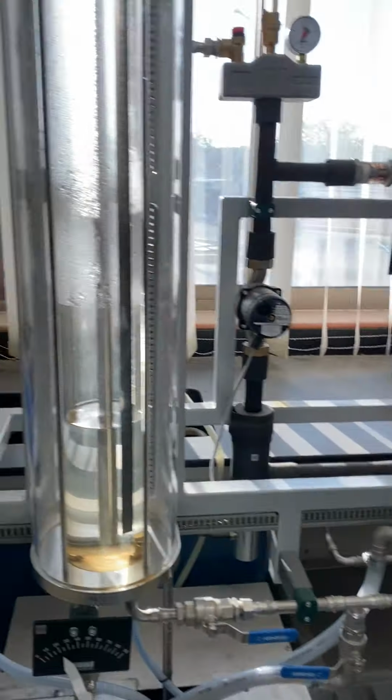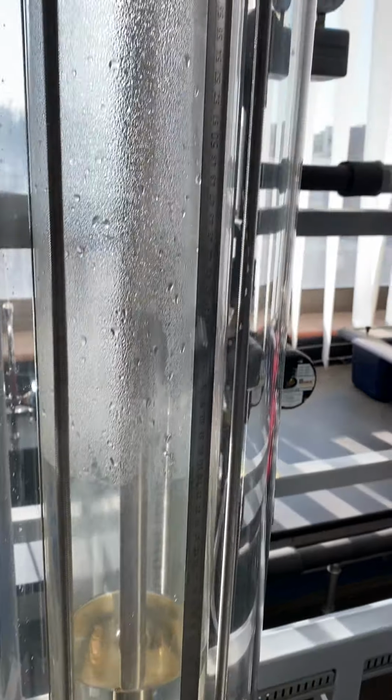When they hit the medium to be detected, the pulses are reflected back and guided to the sensor again, and the time between sending and receiving the pulses is directly related to the travel distance and so the current level. So what happens here, guys, is that this sensor right here, as we said, is connected to this rod.